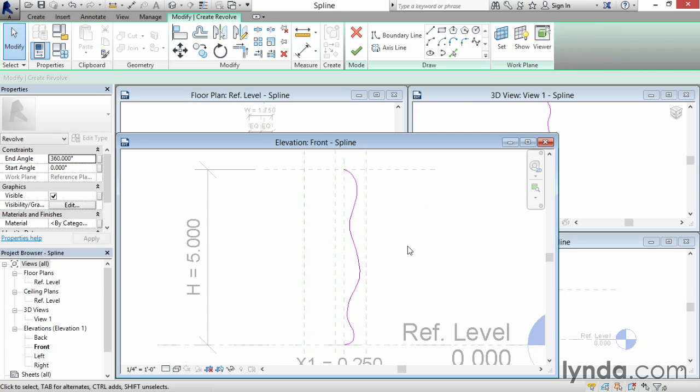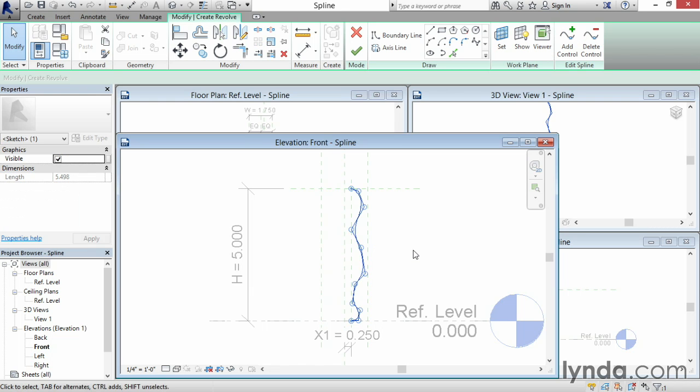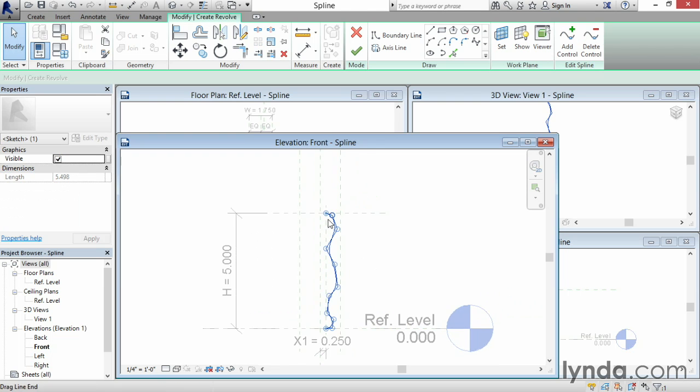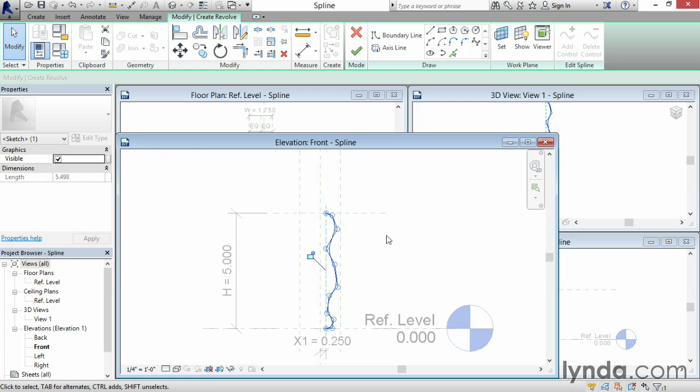The idea behind a spline is quite simple. The splines have a built-in superpower, which scales proportionally automatically. In other words, that's just what it does unless you tell it otherwise. So I can demonstrate that really easily by selecting the spline. I'll zoom out a little bit, and I'm going to grab this endpoint at the end here and start to drag it. And what you'll see is as I drag this, the shape of that spline, even if I drag at an angle, is being maintained. So all of those intermediate points are unaffected. They all scale proportionally as you stretch the shape. Now, that's great. That's the feature I want to leverage.